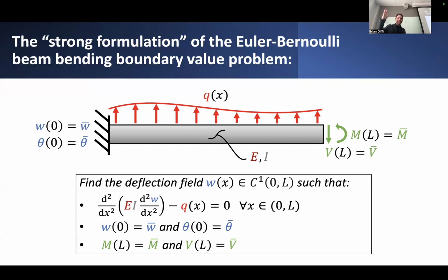But to be consistent in fully specifying the boundary conditions on every exterior end of this beam, we have to specify one of two things at each end. Either we have to specify some kind of displacement-like constraint, or we have to specify some kind of stress-like constraint, and those two things are mutually exclusive. So, for example, in terms of the different types of displacement-like constraints, we can either constrain transverse displacement, or we can constrain relative rotation of the section at one of the ends.